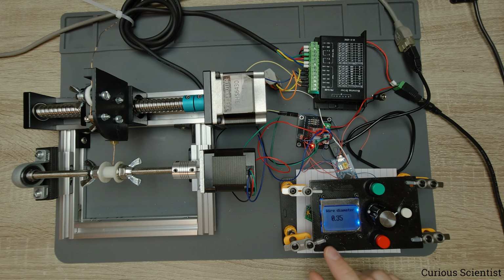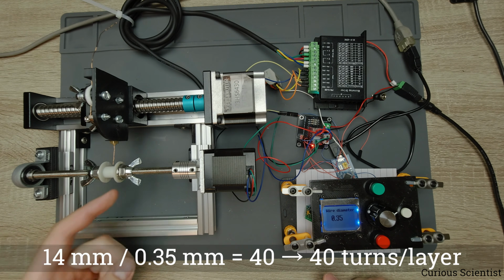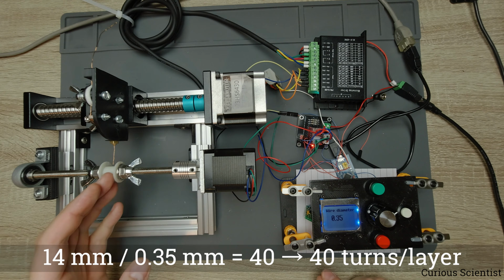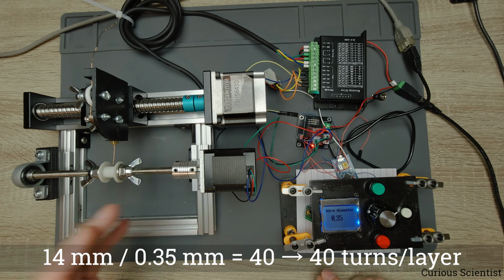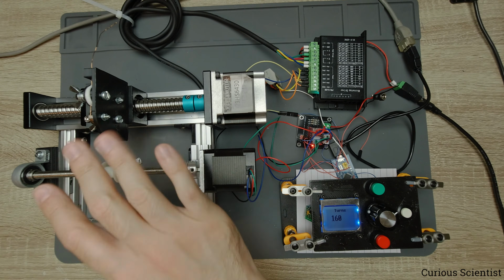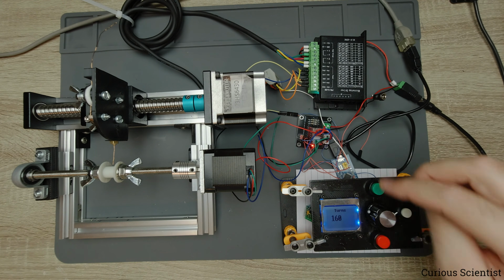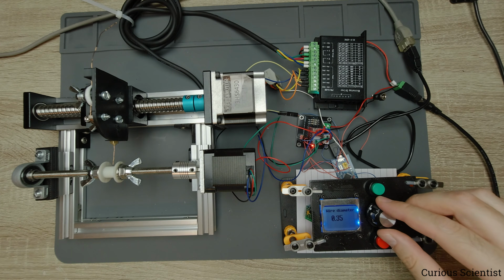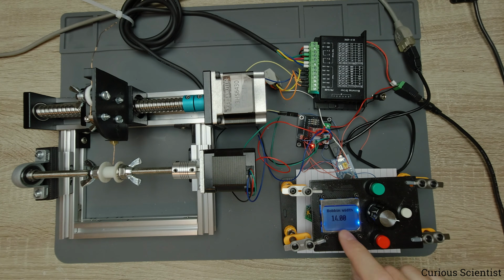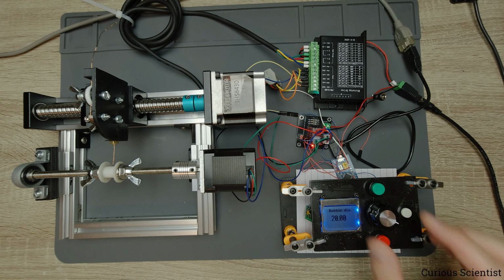And actually, if I calculate the width of the bobbin and the wire diameter, then one layer will need 40 turns. So 160 turns means there will be 4 layers of wire on this thing. In another video, I will show you all the mathematics behind these calculations and these kind of numbers. So then we know the width, so that's 14 millimeters, so that is already inside.